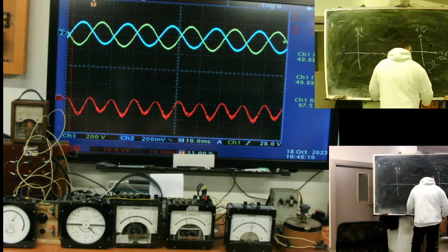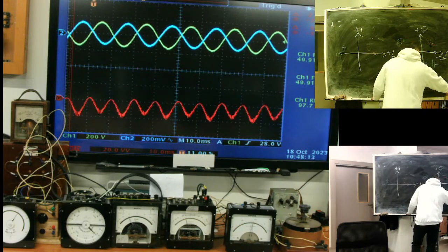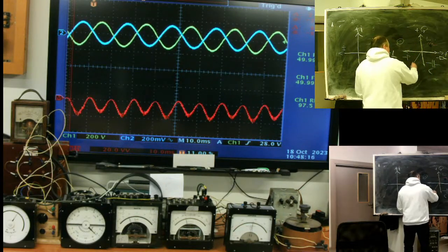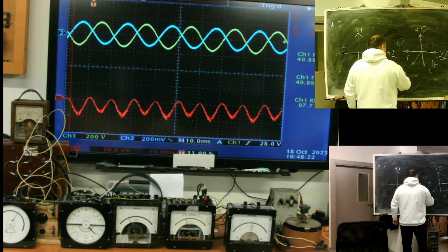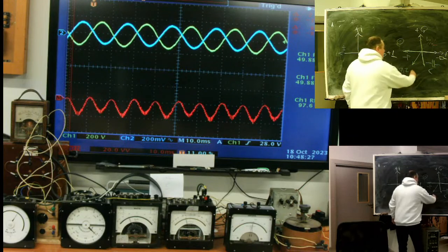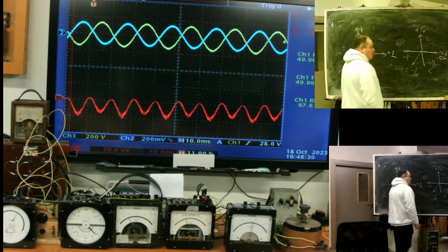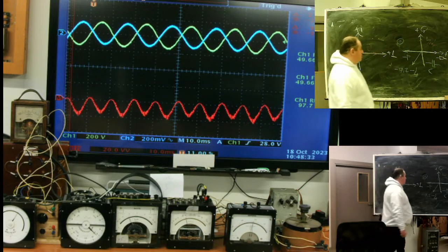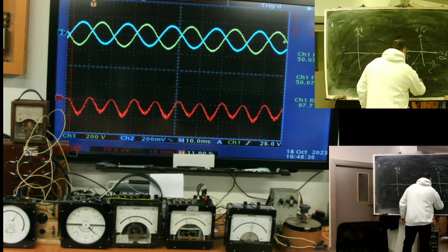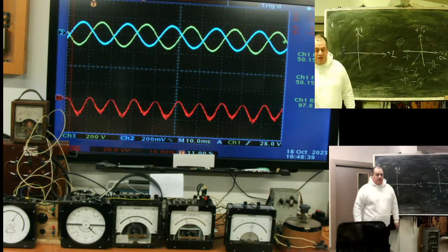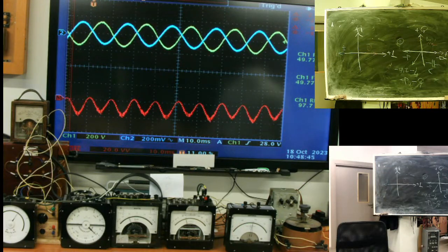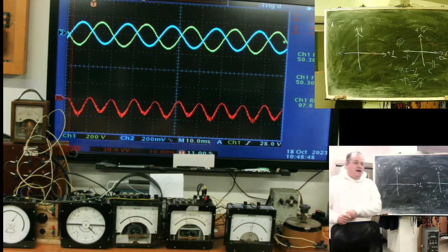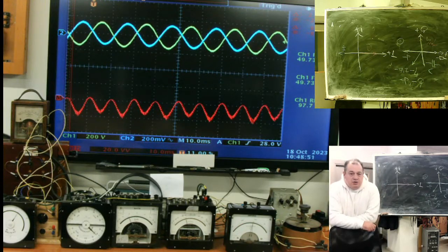At the present moment, I'm here with the power factor minus 0.7. It's a minus coil regime. Regime minus Q. I'm supplying to the network both active and reactive power. It's an overexcited regime of synchronous machine.